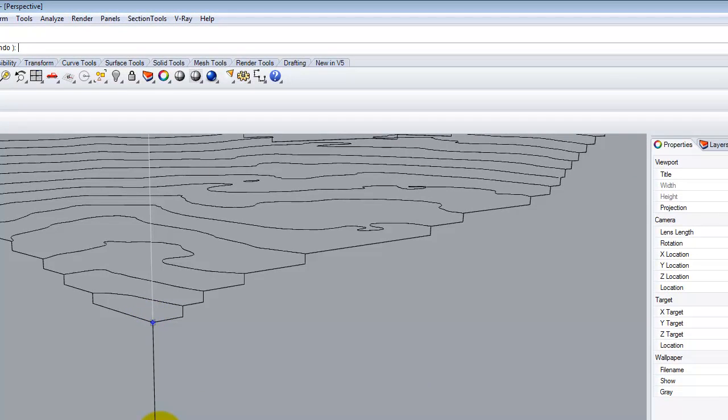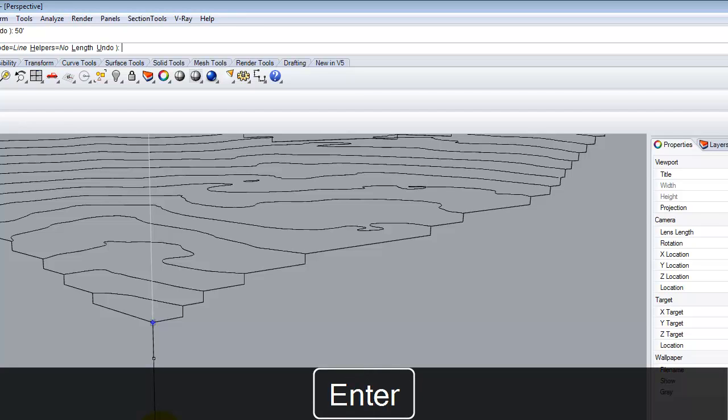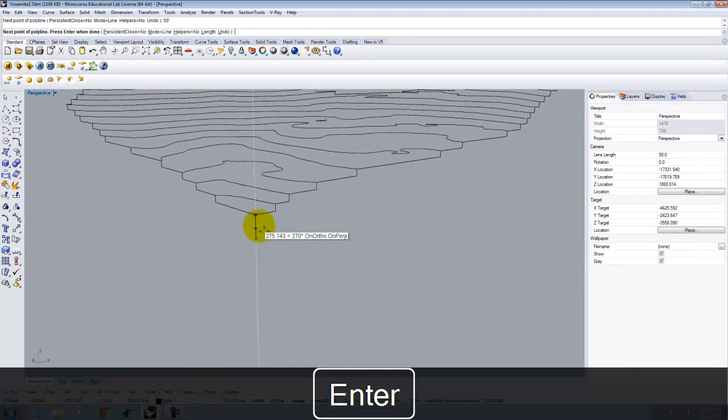Okay, and this dimension is completely arbitrary. Philip, you were asking me, what do you pick? I usually pick at least double my contours, sometimes triple. You could do more. It depends on how tall you want your model to be. If you start to get too tall, it's going to look awkward. So I don't do too much usually, but usually it's a couple times whatever my dimension would be. So my dimension is 15.625 feet. So maybe I'll do 50 feet. I don't know. Nice round number. 50 feet. All right, and it gives me a side there.